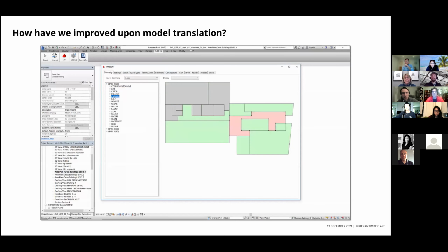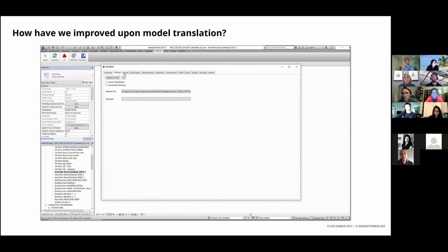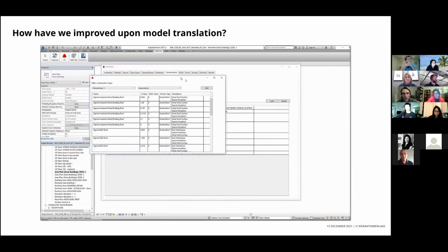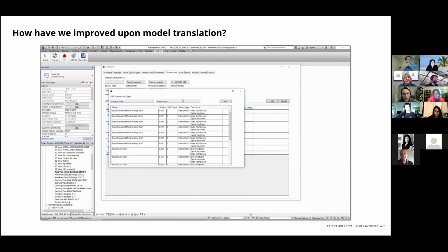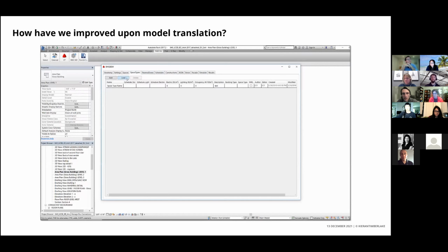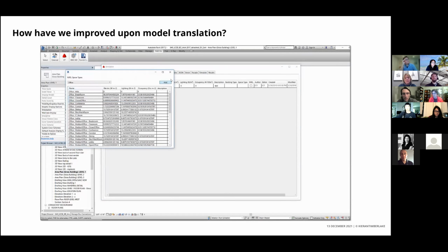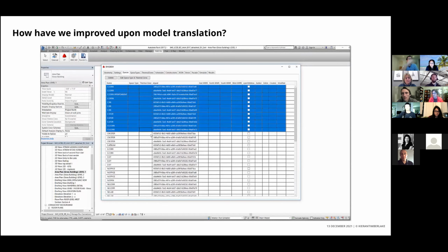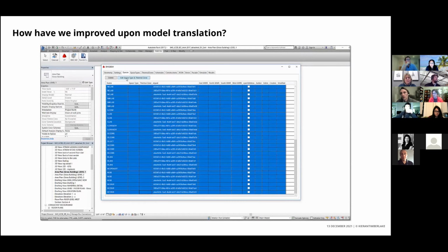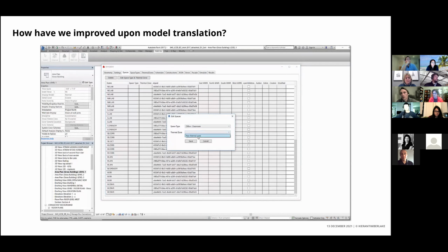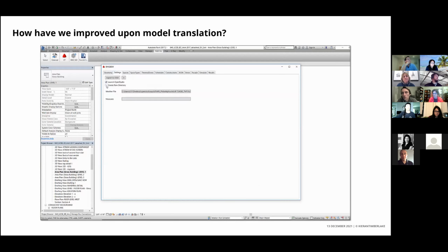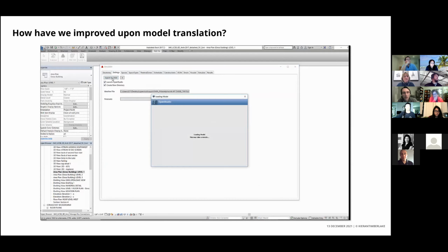Sure, happy to. So in discussing some of those traditional modeling workflow sticking points with our engineers, we've had a number of conversations over the years, and one of the points of friction that we found to be really common is simply about building geometry and reconciling building geometry, thermal zones, and their associated internal loads between an ever-evolving architectural model and an energy model.